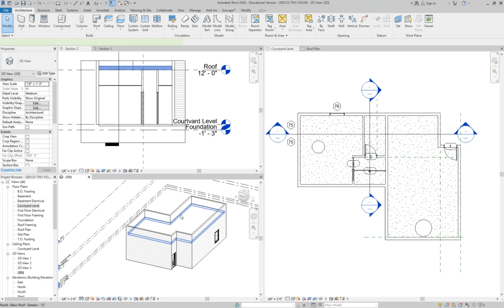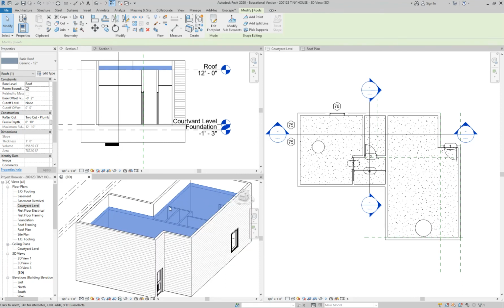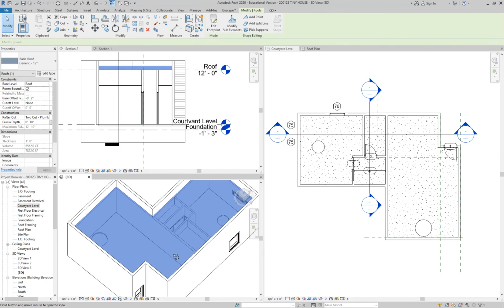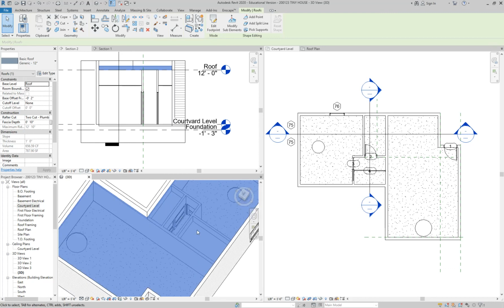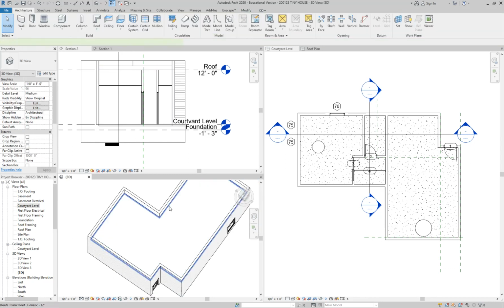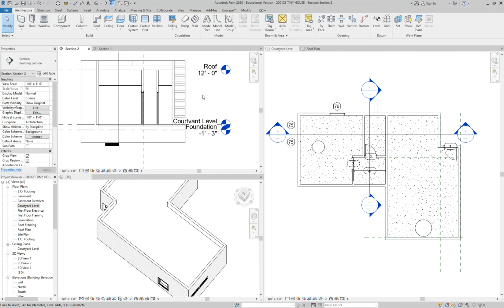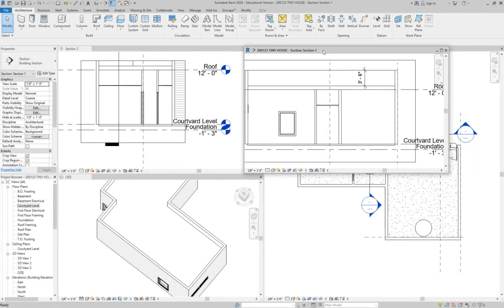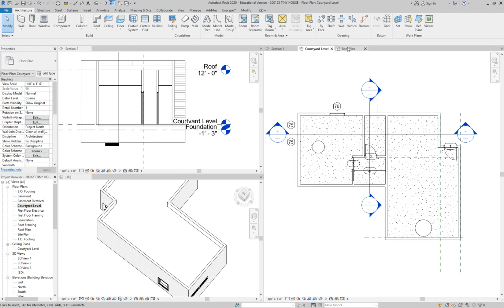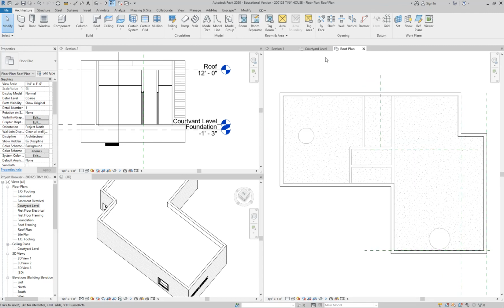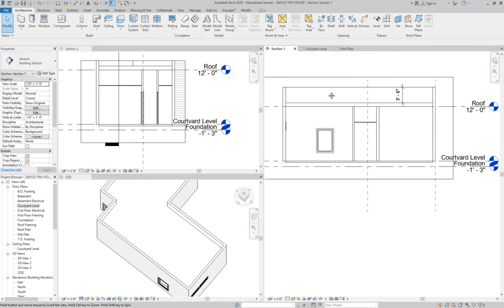You could, no, we're not going to hide the roof. You could click on your roof in your 3D view, and you can kind of tip it to see the ceilings below. Essentially, sometimes just by selecting the roof, it gives you X-ray vision, and you can see the ceilings in there too. But I think the section's a little bit easier to see it. I like how you just dragged your section view over. Oh yeah, so let me put it back where it was. I don't think I've ever done that before in Revit, to be completely honest. I do it in other views.